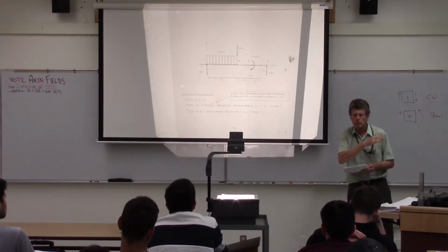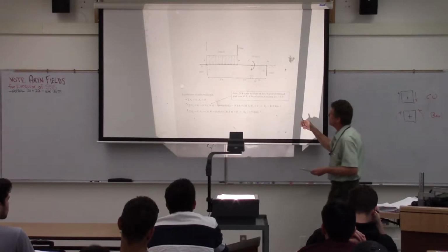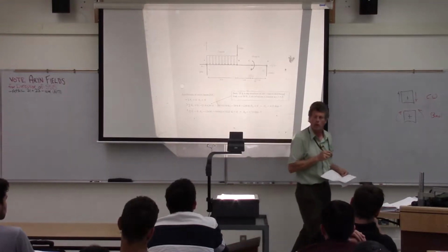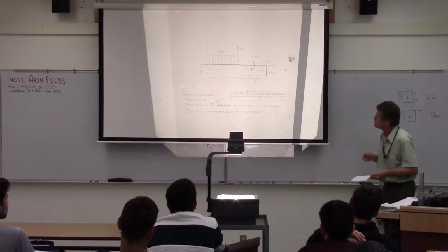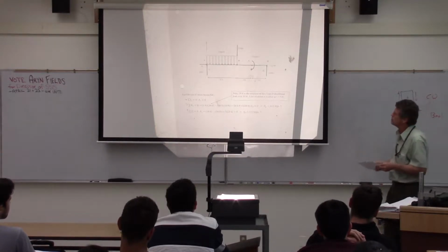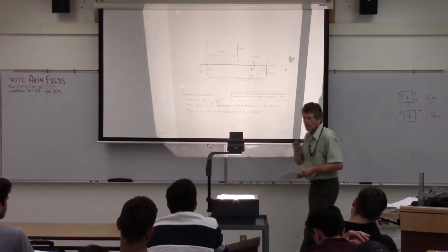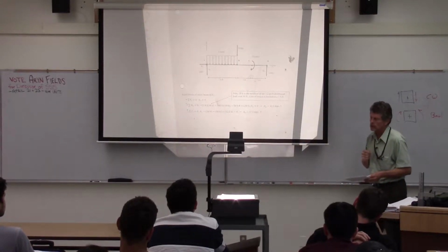So when you draw your free body diagram, the first thing we're going to be doing on almost every one of these problems is coming up with our support reactions. Once we get our support reactions, again, think of them in terms of forces. Look at your free body diagram and say, I need to make 3 cuts in this particular case.